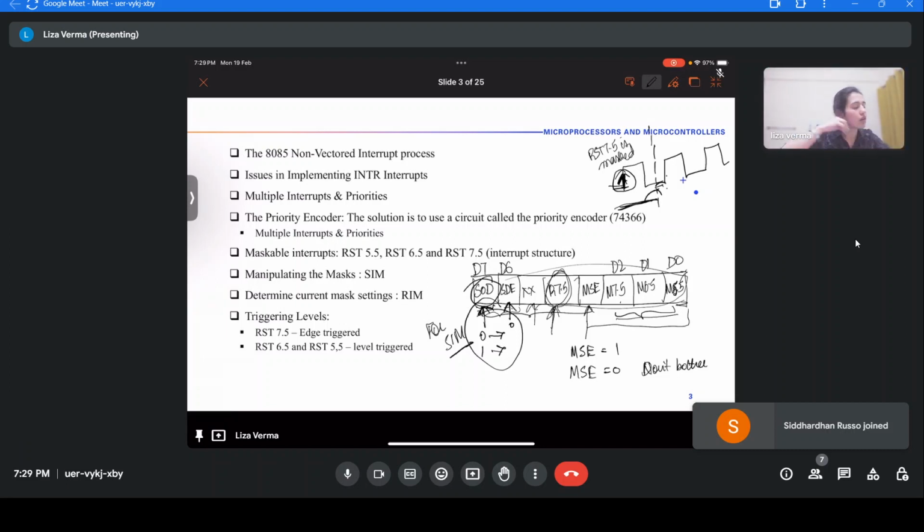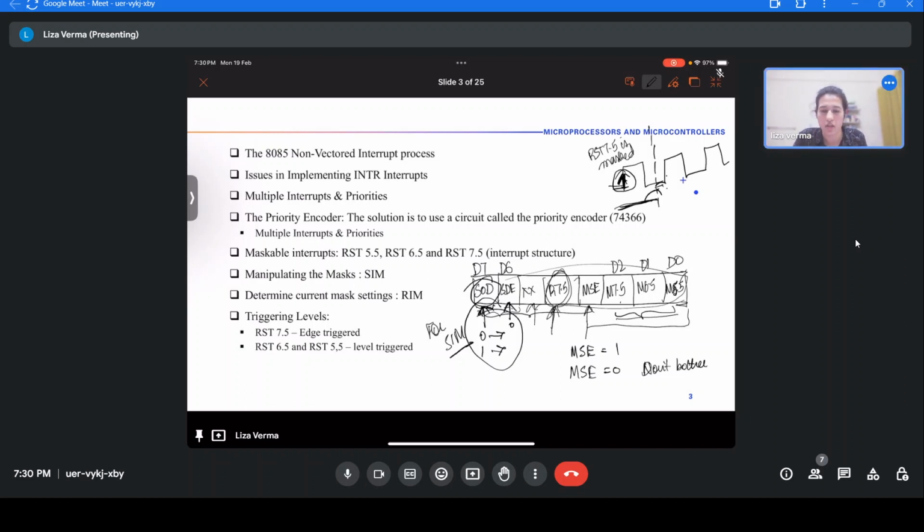So if I keep 1 in SOD, then if I make the SDE toggle, say for 100 microseconds SDE to be 1 and the next 100 microseconds SDE to be 0, if I keep toggling the SDE bit, will I see the same toggling in SOD, ma'am? Like previously, I had kept 1 and kept SDE high so that I can see 1 in the SOD. The contents of SOD are not changing, you're saying.